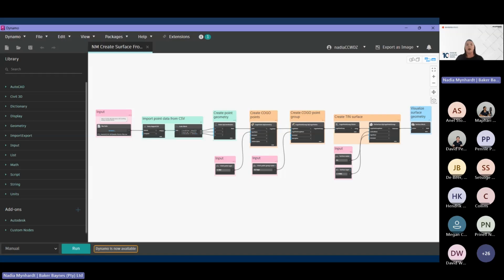So let's say, for instance, I want to automate the creation of a surface in Civil 3D. Obviously, the first thing we are going to do is import points. Then we need to tell Civil 3D, this is the X and this is the Y and this is the Z, for instance. And if you're a perfectionist like me, I also want the points to be on a certain layer. They should also be grouped together. And I want it to be this name, for instance, and this color. You can think of all the things that you want to change. But then I also need to tell Civil 3D, please create a surface now for me from this point group. And this is what the surface name should be, and this is the color it should be and the layer it should be on.